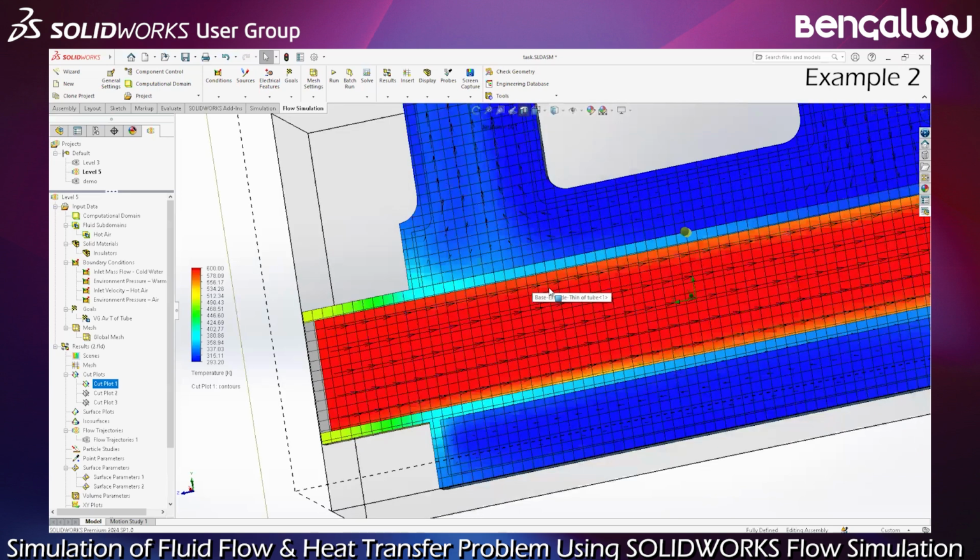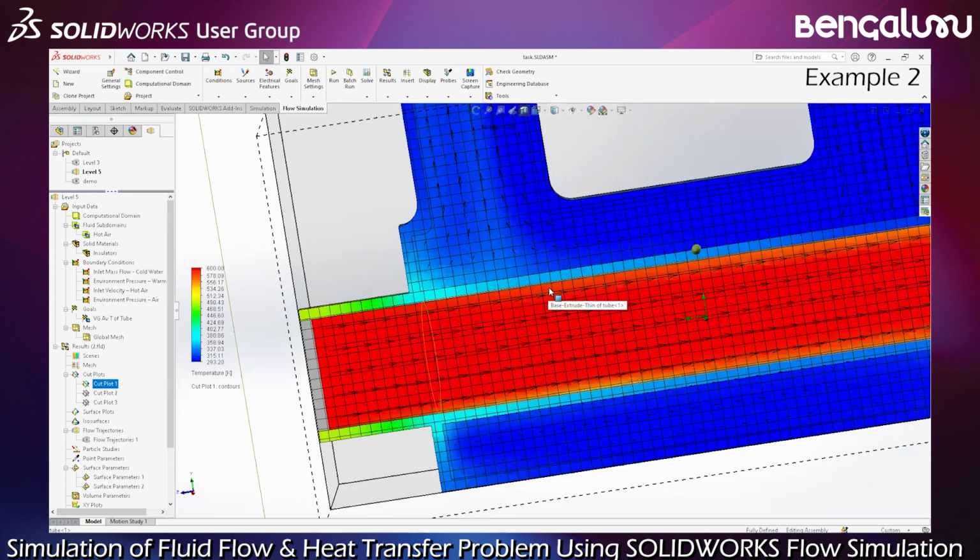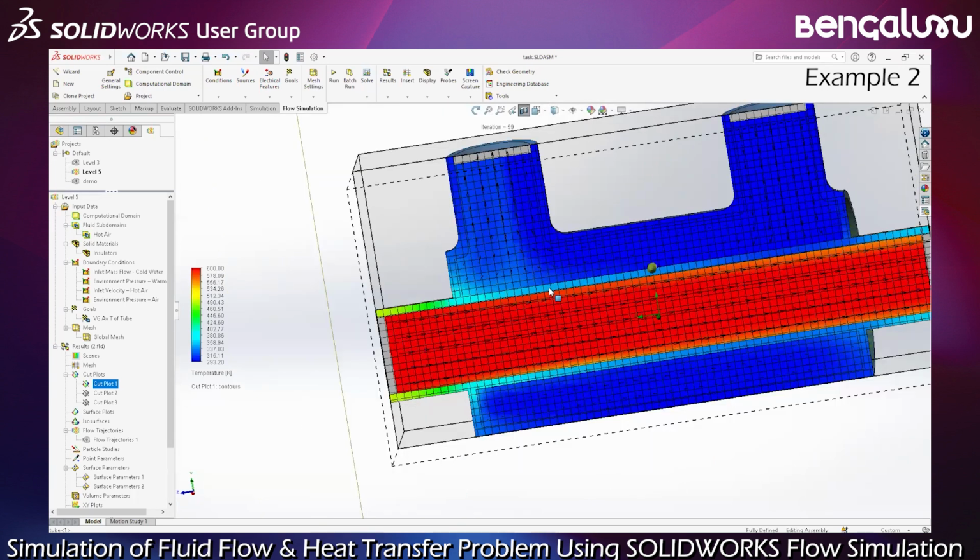Of course, we can do like we saw last week. If I have to validate this, what I will do is try to refine the mesh on the walls, because the exchange will be calculated on this area.